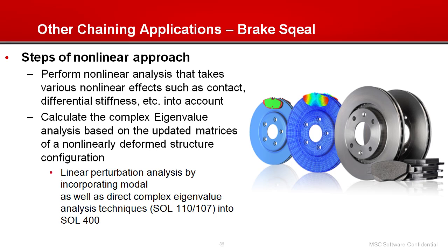Contributory factors are forces at the disc pad interface, temperature, caliper stiffness, variation of friction coefficient, disc rotational speed, and deceleration. Other variables in brake squeal may include damping layers, dust accumulation, piston pad, contact condition, grease, and what have you. This is another application which really deserves its own webcast to discuss the details of the analysis chaining.